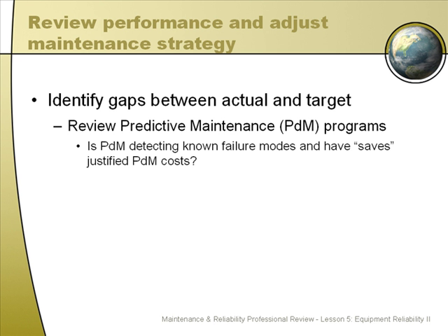Well, this is kind of an error in thinking, because predictive maintenance is really designed to monitor equipment and identify when something changes so that you can plan and repair it on a schedule. It's really not designed, as it's used many times in reactive maintenance, to find a problem and then predict how long the production process can run to get away with something before they have to fix the failure. So, another thing to keep in mind is the predictive maintenance program is only going to provide value if it's built on top of a process that fosters proactive maintenance, because the idea behind predictive maintenance is to eliminate failures, not pass them on as long as possible.